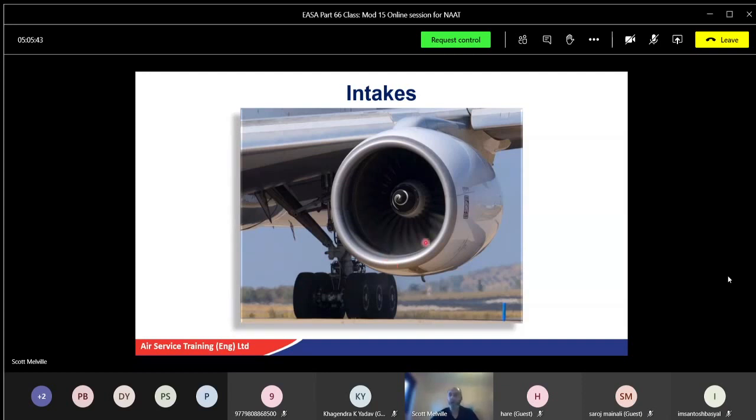If you find lots of oil at the front, well, that means the oil is dripping out of the bearing. If it's dripping out of the bearing, there's a good chance your labyrinth seal has worn. All right. And the debris that comes off the labyrinth seal will probably be found in the chip detector in the oil system, so you can relate to where it's coming from. You will maybe get a little bit of oil at the front, not always, but sometimes you will. The more oil you find, the more wear there is, and it will only get worse. Okay, so again, that might need to be highlighted. So that's a good indication.